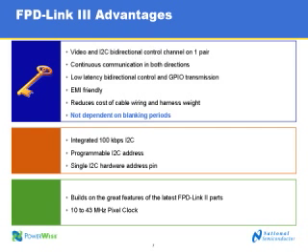Coming back to one of the advantages that you show at the top, not dependent on blanking periods, can you tell us a little bit more about why that's important? Sure. So if we are continuously sending both GPIO signals, so control signals, from the system host controller to the remote device, and we're also allowing a continuous stream of I2C control data to happen. If we were to have to wait for video blanking, that would slow down the transactions and would also limit the timing of the control signals that could be sent to the remote devices. This is especially critical in camera systems where you have multiple cameras that need to be synchronized. Oh, okay, gotcha.